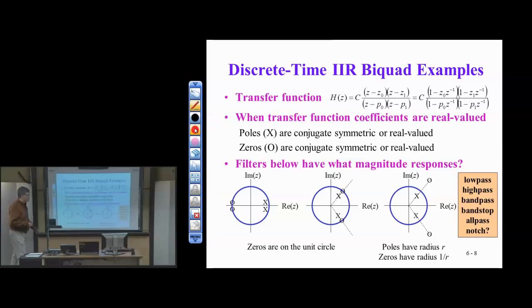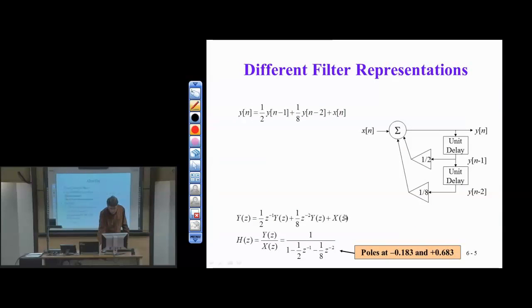One of the treatments is to take all the recorded music that the person with this condition would listen to and pass it through a notch filter to remove the frequency at which the ears ring. If that frequency is present in the audio they're listening to, it causes a resonant response, so it grows really strong almost without bound. It's quite painful when that frequency is present with any strength. So you can pass all the recorded music through a notch filter and get rid of that particular frequency to make it easier to listen to. It's an application.